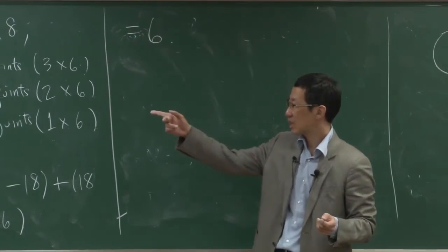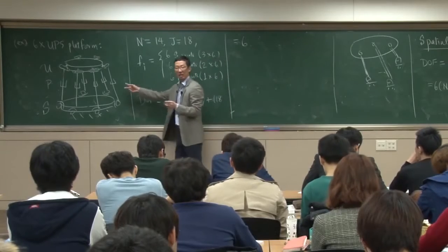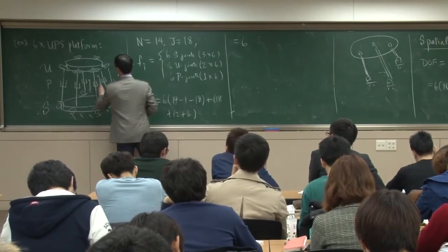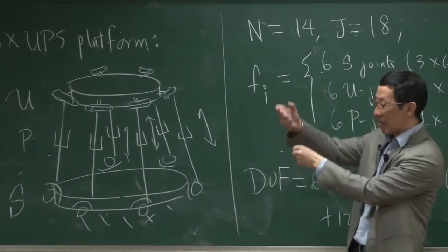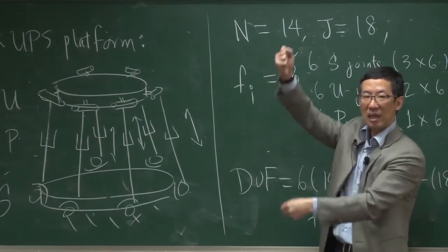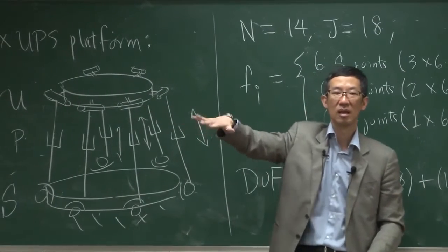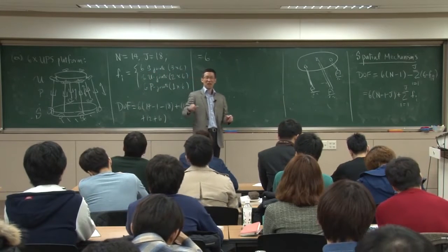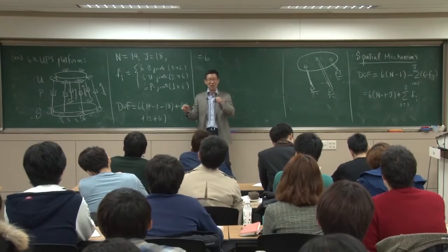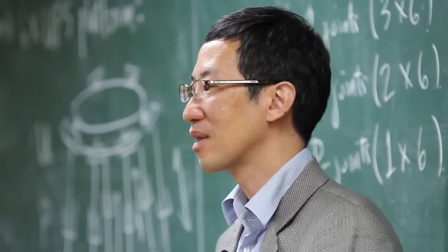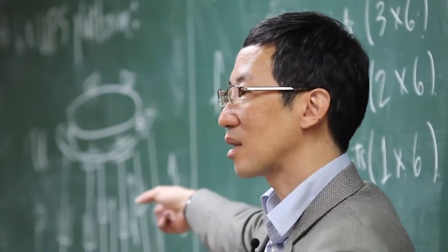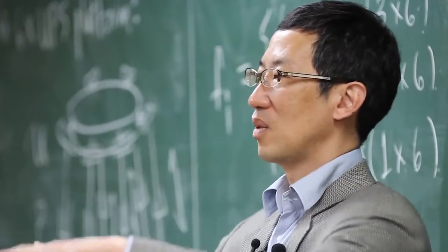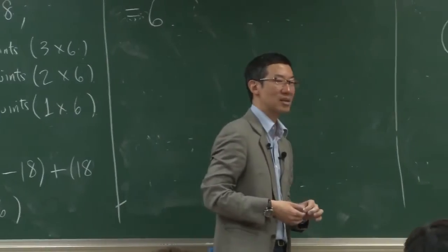Now in these types of mechanisms, usually it's the P joint that's controlled. So these P joints have motors. And as these legs increase and decrease in length, this platform moves. Now, have you guys tried the driving simulators in these game rooms? Usually they're built on these types of platforms, right? These legs move, and you're sort of moving on top.